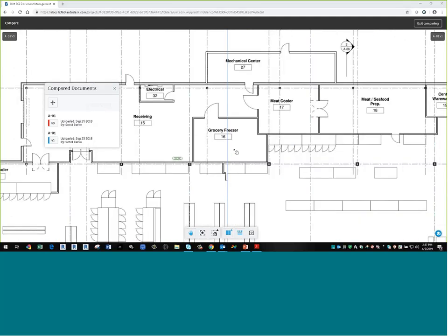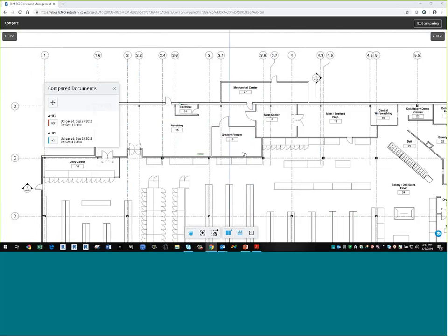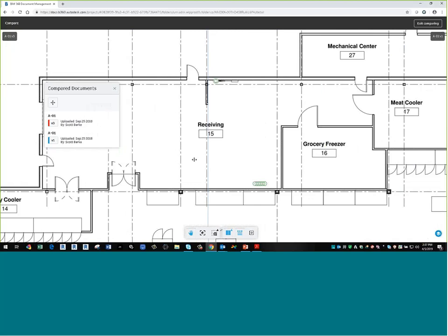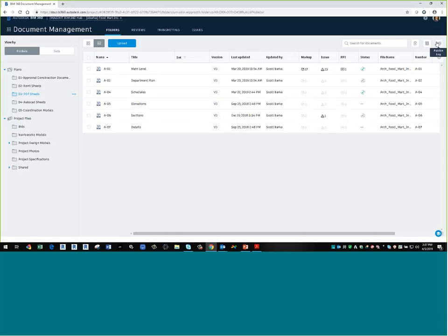That's one of my favorites, that I'm instantly able to see all the changes in the drawing and understand where I have to pay attention, because now I know where to go specifically. For instance here, they put electrical panels in, but in this jurisdiction we have to have a box around it, basically walls. It has to be its own room. So that was the addition. They added walls around the electrical area. And again, I can exit that.